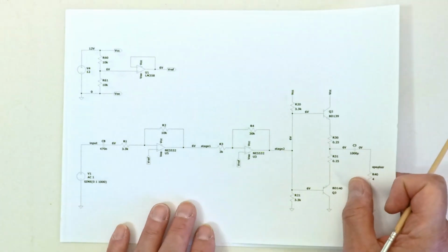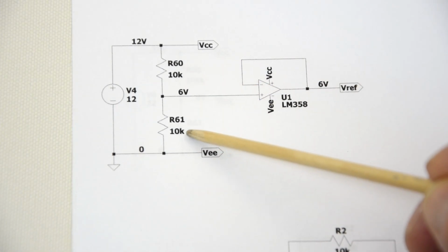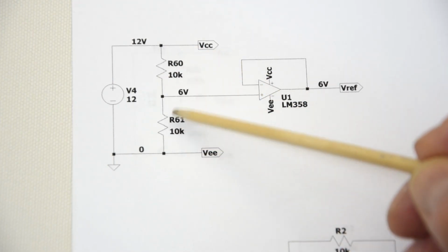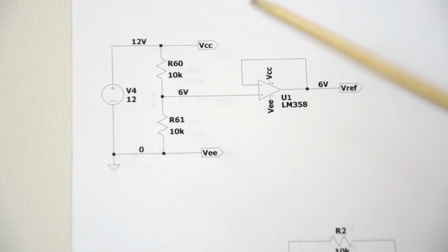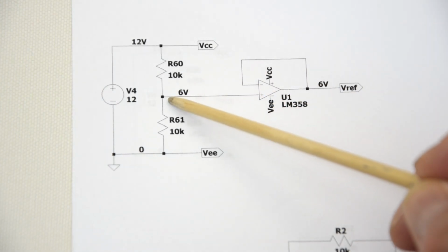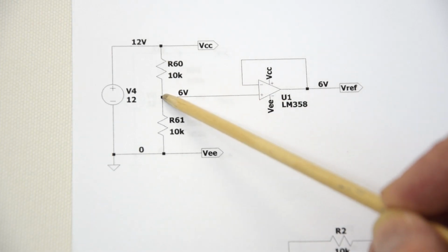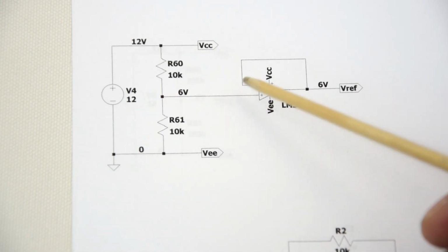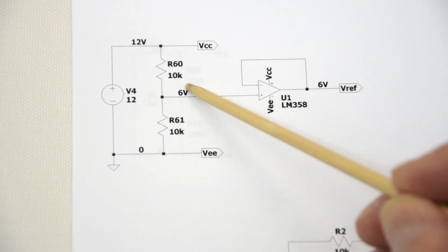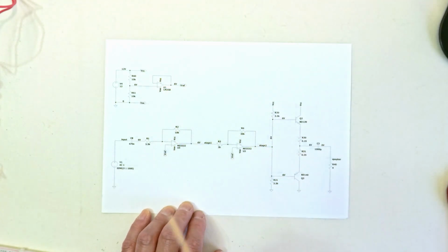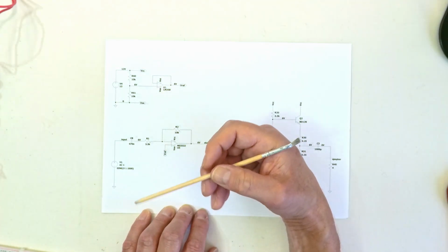Well, I've drawn it here. I lower the resistor values of this voltage divider. So there's 10 times more current going through it, but still well below 1 milliamp. So it's nothing to worry about, but it makes it harder to disturb if there is some current drawn by this op-amp. The only op-amp drawing current from this voltage divider is this one op-amp, and not all the 4 op-amps used in the amplification of the signal in this amplifier.